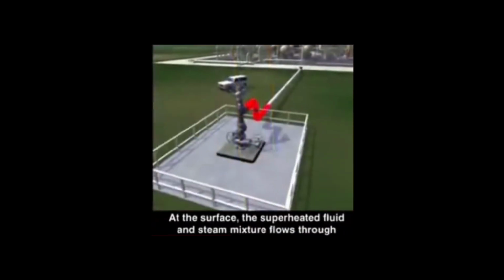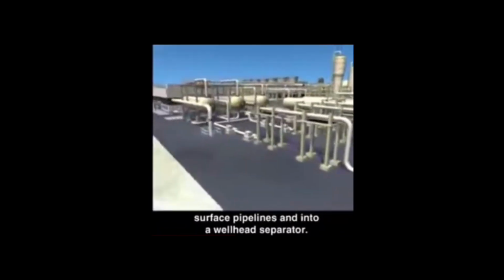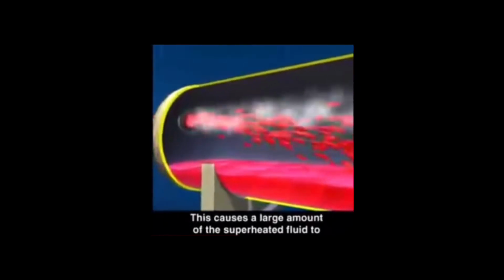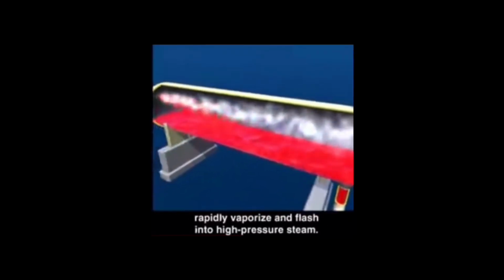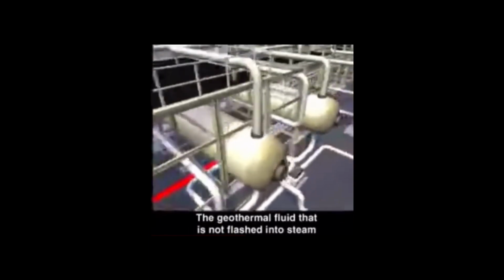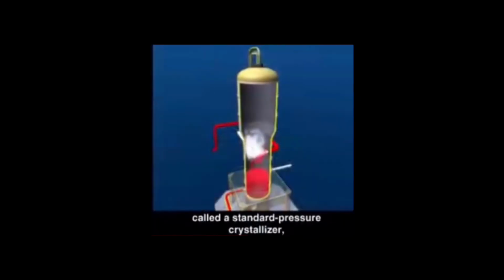At the surface, the superheated fluid and steam mixture flows through surface pipelines and into a wellhead separator. Inside the separator, the pressure of the superheated fluid is reduced. This causes a large amount of the superheated fluid to rapidly vaporize and flash into high-pressure steam. The geothermal fluid that is not flashed into steam in the wellhead separator flows to a second vessel called a